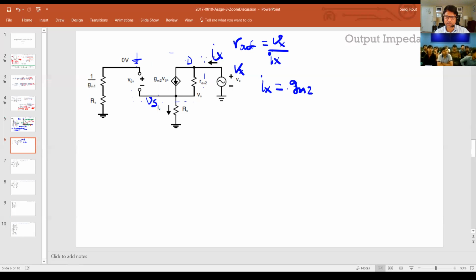So all it is is minus the source node voltage, minus VS, plus the current flowing through the output impedance of that transistor, which is Vx minus VS, times 1 over RDS, or I can just write it as GDS2. And GDS2 is nothing but the reciprocal of your impedance, 1 over RDS2. Sometimes it's easier to write it that way. So that's your first equation, right?